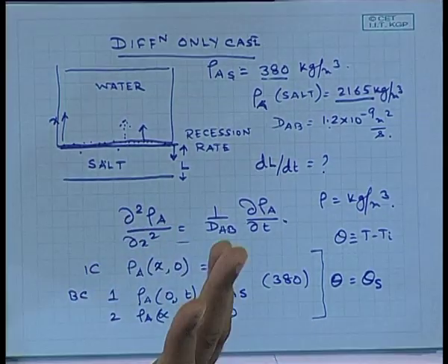You have solved that problem of a semi-infinite solid where one boundary is suddenly brought to a new temperature, and you will see if you just look at your class notes from the other part, that the solution for that is the error function. So, what I encourage you to do is look for similarities.